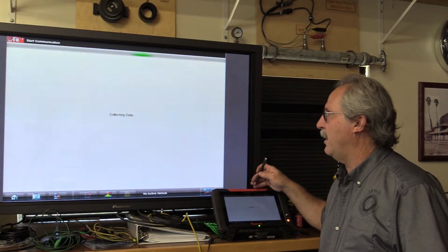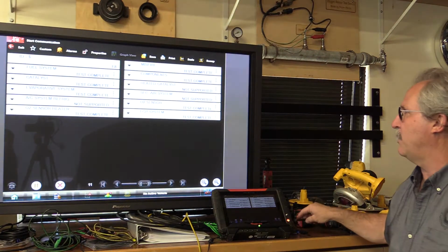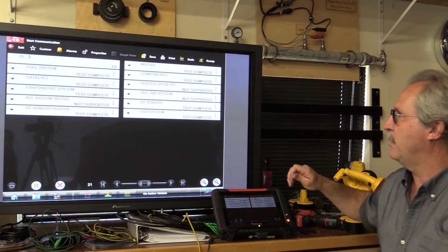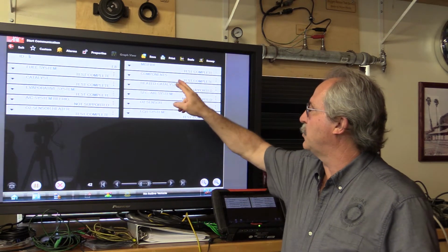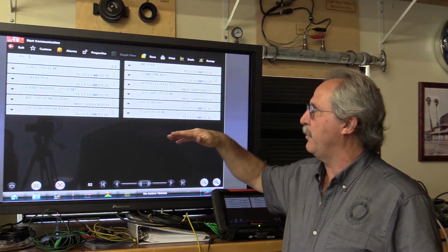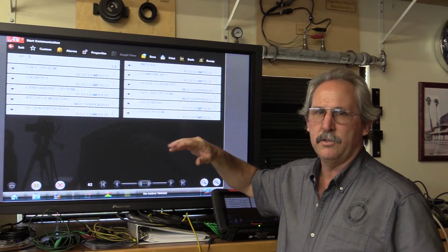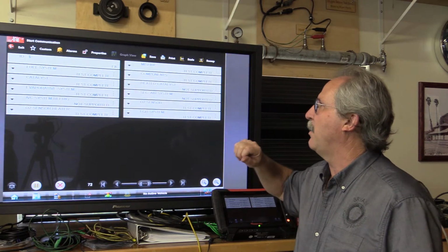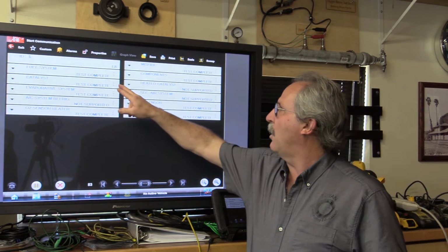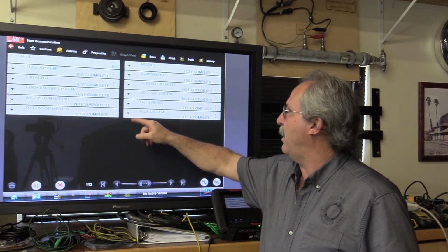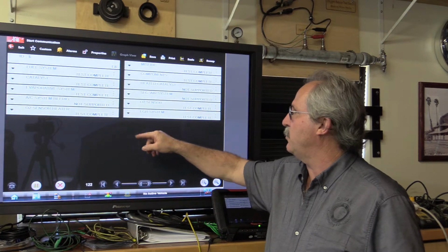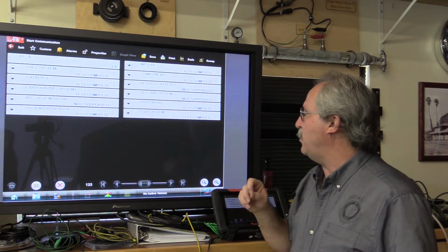So I'm going to click on that, and I'm going to see all the different monitors that are supported here by OBD2, and I have Misfire, fuel system, and comprehensive component are complete. Those are my continuous monitors. Now my non-continuous monitors that I actually have to worry about are catalyst, fuel evaporation, heated cat, secondary air, AC system, O2 sensor, O2 heater, and EGR.